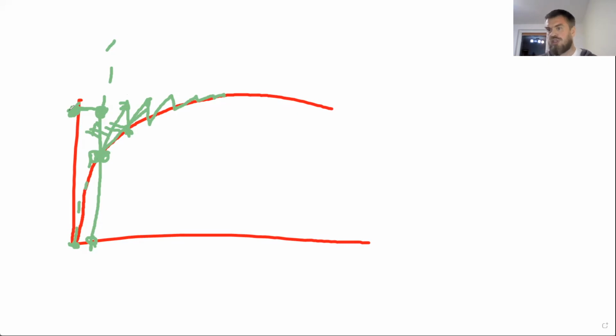And usually you will apply your load in several increments. So clearly this will be a problematic thing, because not only do you get iterations that last as long as a linear analysis, but you have many increments and each has many iterations. So this all multiplies the time a lot. And this is why computing.